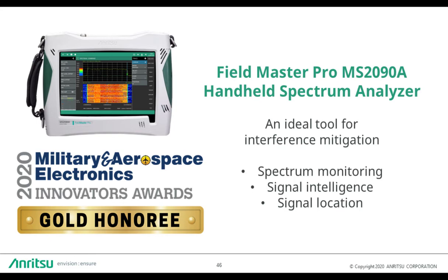Actually, counting the number of them can be difficult from a spectrum analysis standpoint. Generally, what you will need is very smart software that can detect down to the level of actual identification of the devices, and that depends on the type of transmitter, because not every transmitter has specific IDs. So if all you know is the spectrum, counting the number of transmitters will be difficult. You may have to do elimination one by one. If you can decode those signals to get actual IDs, you may be able to get more detail there, but you're getting into some pretty high-level signal identification.